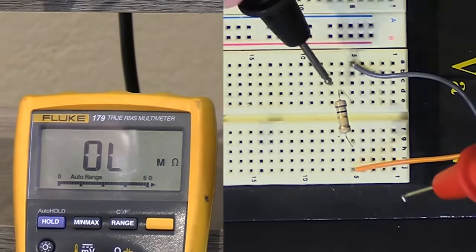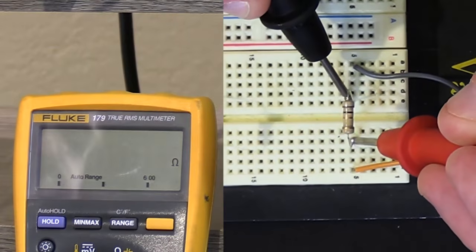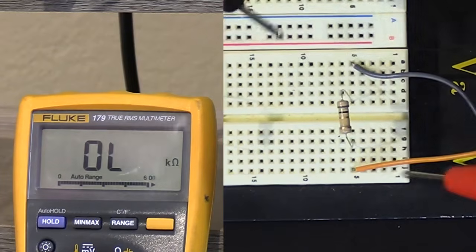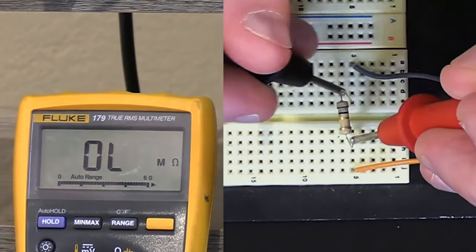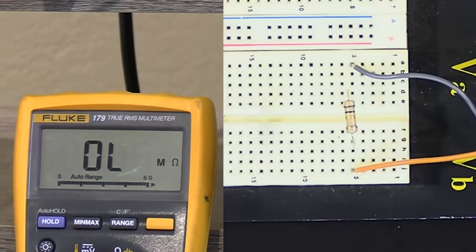It's not exactly 1 ohm for a couple reasons. Because I'm touching it with this probe, and so I have a little bit of resistance in the contact point. And also, these resistors are not 100% accurate. There's a tolerance to all of them, so they're not exact values. The bands decode to tell me this is a 1 ohm resistance, but when I measure it, it's always going to be a little different than the theoretical value, but it's very, very close to 1 ohm. In fact, that's going down, down, down. You can see it going down. If I push a little bit harder on it, if I really give a good contact point, you can see it gets down very close to 1 ohm.